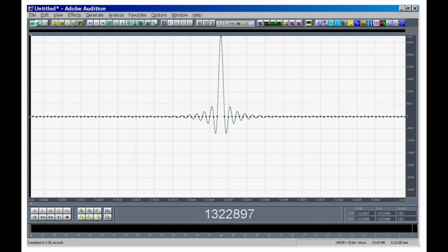However, it is not a good idea to remove completely the fade-out. At the end of the sweep, the final value computed could be not zero, and consequently the sound system will be excited with a step function, which spreads a lot of energy all along the spectrum. A solution alternative to removing the fade-out is to continue the sweep up to the Nyquist frequency, 22,050 Hz in our example, as the sampling rate was 44.1 kHz, and cutting it manually at the latest zero crossing before its abrupt termination. This way, no pulse of sound is generated at the end, and the full bandwidth of the sweep removes almost completely the high-frequency pre-ringing.